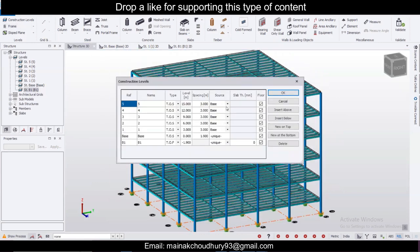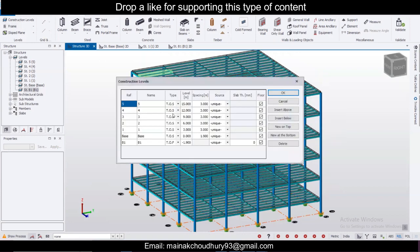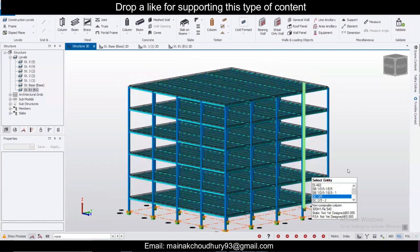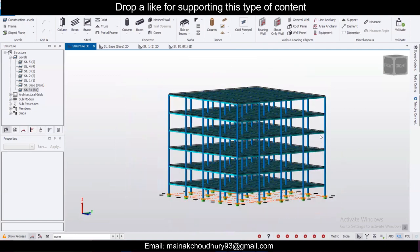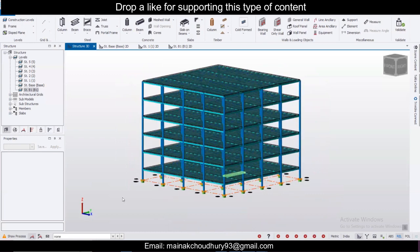Go to construction levels and make them unique. It is a very important step. Otherwise, you cannot make any unique changes in any of the floors. So you can just click on OK. Again, you can check that all are unique or not. It's a very important step. You can see all are unique now. So now this model has been completed.